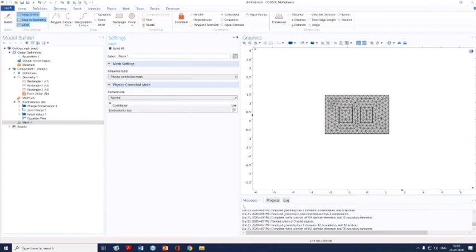Yeah, I understood 2D and 3D geometry problems, but what is the necessity of 1D and 0D? So, for example, as I was mentioning, with 1D, if no variables are changing in the other two dimensions, then 1D modeling will be required. Just as an example, let's say some pipe flow physics, wherein you know that the flow across the cross section is not changing, but it is just changing along the length itself. In that case, 1D simulations will be required.